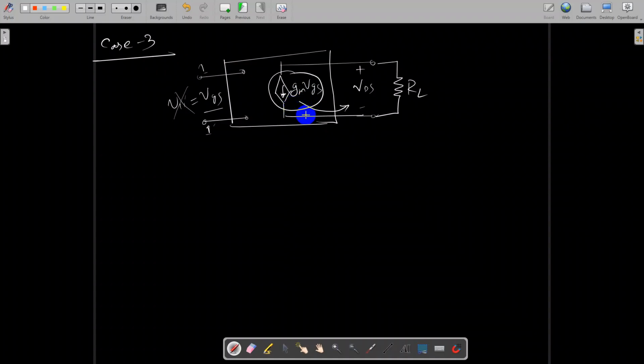Okay, the negative resistance. Now in a small signal model, I can say I2 times V2. So what is this I2 from this side? This is nothing but GM times VGS, but there is a negative sign. So negative GM times VGS times this V2. This V2 is nothing but VDS, sorry, it is small d, vds.